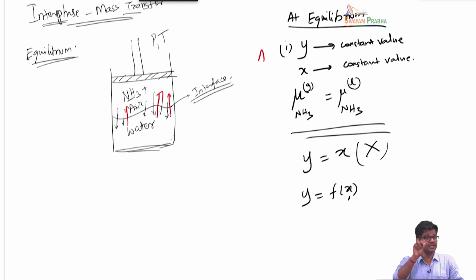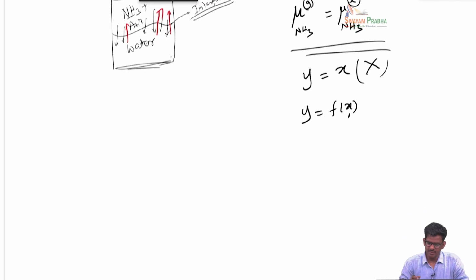So now you have changed the equilibrium composition by putting some extra ammonia. Now that extra ammonia will have to be redistributed again to the liquid. So now another new set of equilibrium will start happening. More transfer will happen, and then the system will reach another equilibrium state, in which case the composition at the gas phase and liquid phase will be different from before you injected them, because we have changed the initial composition.